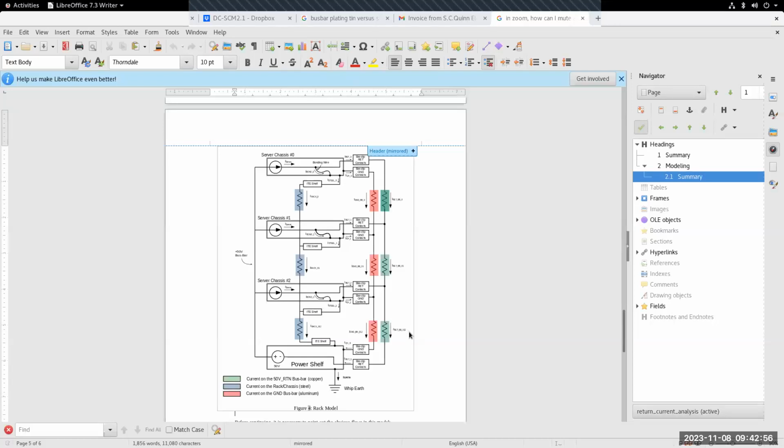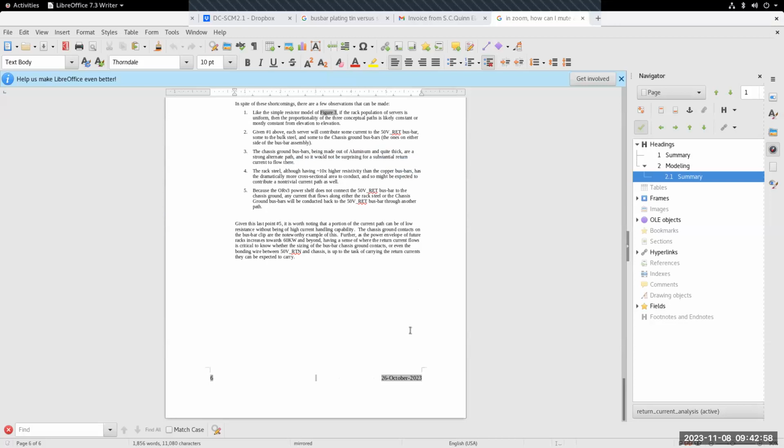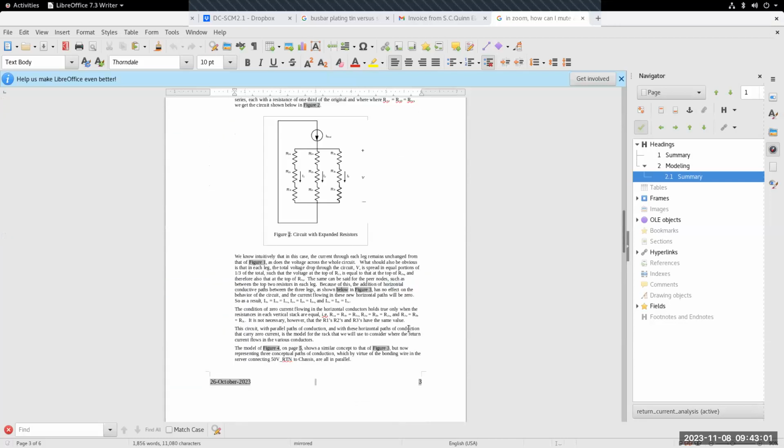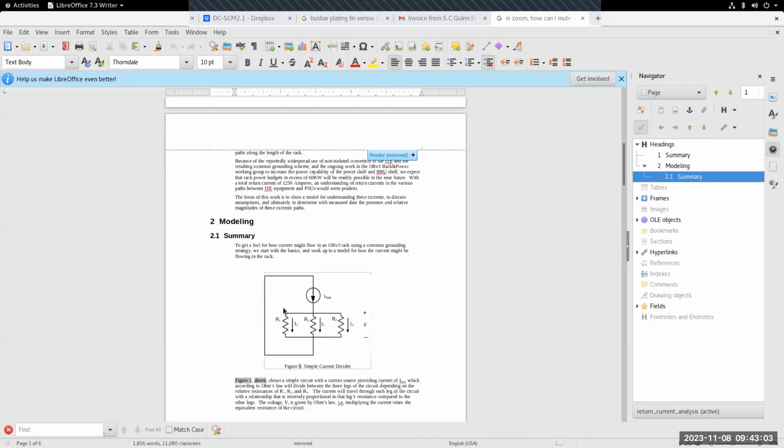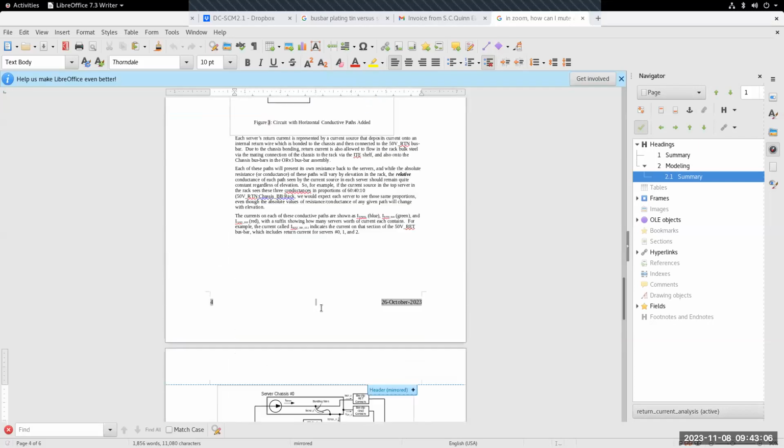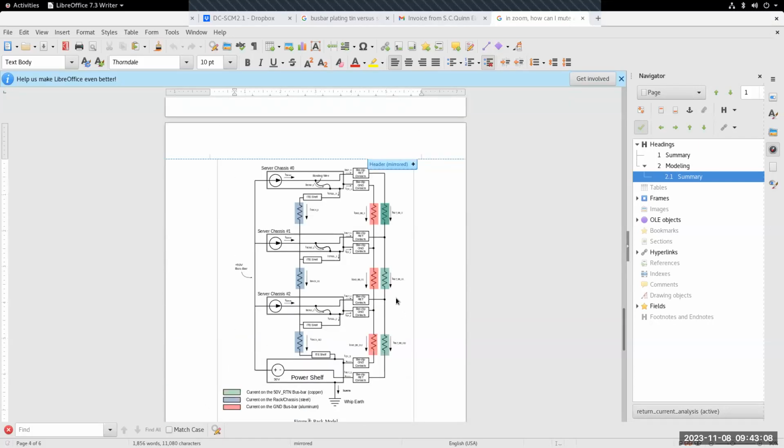That's kind of where I was at, and I was in the process of, I can't remember if I did that. I was starting to do the math and figure out what the equations look like, and it's not as simple as what I've shown here. Because each of these resistances, like this is a resistance of a 10U section of return bus bar, say the green one, is a super small resistance, and I'm showing other things here as not resistances. Like, oh, these have zero resistance, but these have actual resistance. Well, we know that that's not correct.